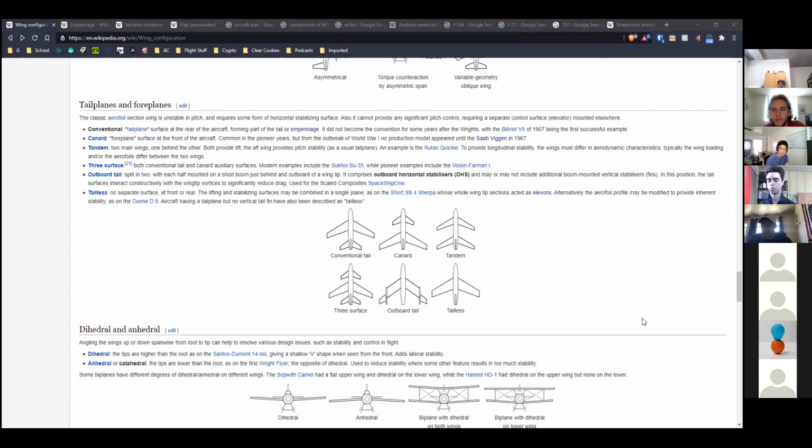So I think there's not enough research on our scale of planes, where if we did do a tapered wing, we don't know what the added benefit and what the cons would be with that. Definitely something we should look into now that we have the availability to produce it rather quickly, because we have the laser cutter in close proximity to us.